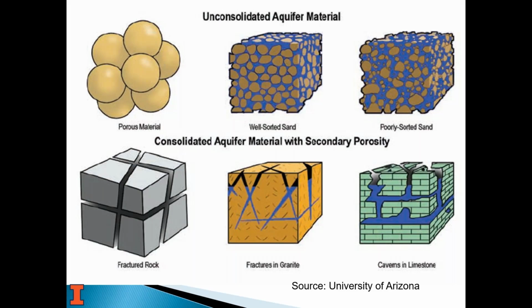And when the glaciers melted, the rivers ran so high that there are areas much wider than the rivers today that may have these sand deposits from when the glaciers melted, hundreds of thousands of years ago. But how that all fell out and is sorted makes a difference in how easily water can flow through it, and whether it has secondary porosity.